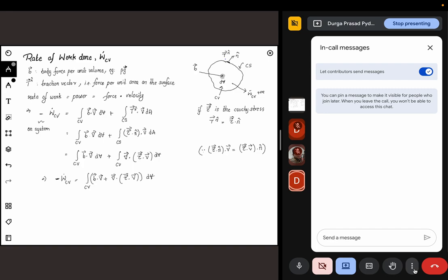this particular force again. This particular term here, we cannot apply the Gauss divergence theorem directly. So we need it to be in a different form. So what we try to do here is introduce another tensor, tau double bar. I'm using a double arrow to say that this is a tensor and not a vector. In 3D, it will have 9 components, whereas a vector will have only 3 components. So this particular tensor is like your stress tensor.